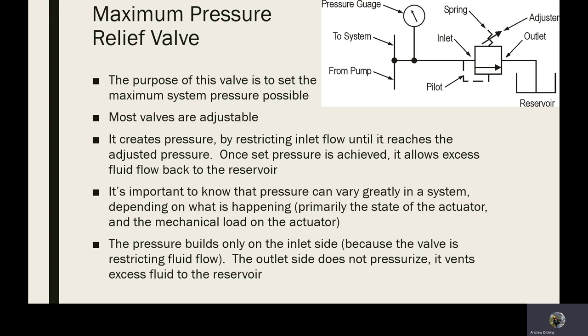So a maximum pressure relief valve is a pilot operated valve. They're required in a hydraulic system. You may have a sealed unit in a hydrostatic system that you cannot adjust and has been factory set and has the paint on the screw on top of it. Yes, if there's paint on the screw, don't take the paint off the screw because you void the warranty.